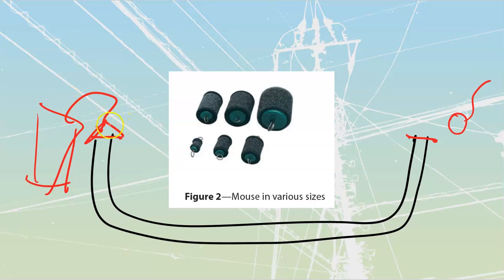What you should do is always start by blowing, expel. That's going to push out any sort of water, fumes, dust, stuff like that. Push it out the other end. Make sure whoever you're working with knows that you're going to blow the conduit out first so they don't get drenched when you push all the water out over top of them. But push the water out first. Then after that, once you push that, you can pull through. You should have safe air.